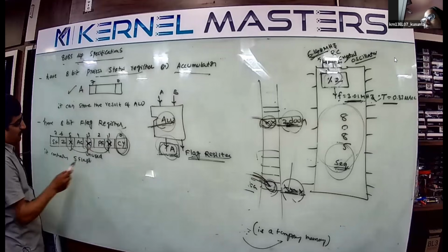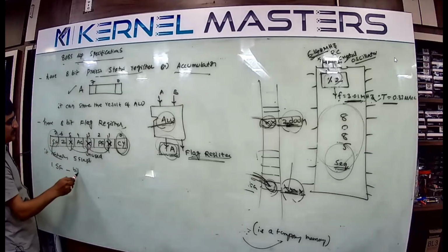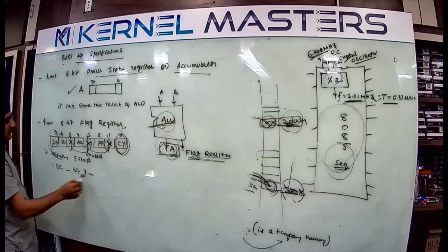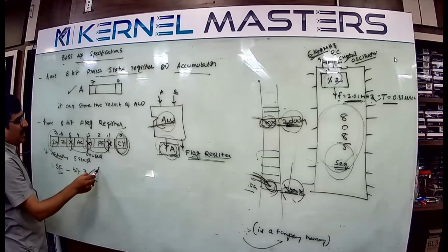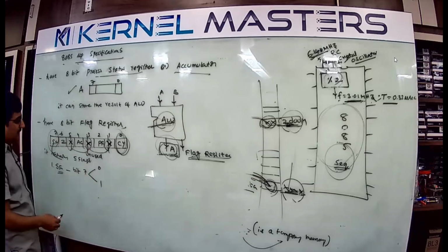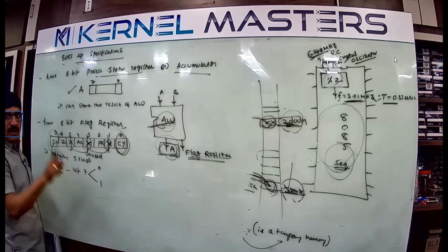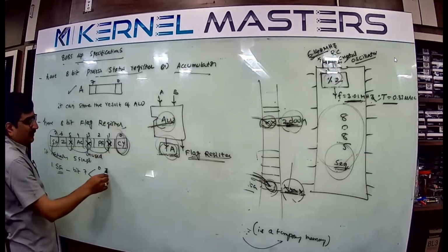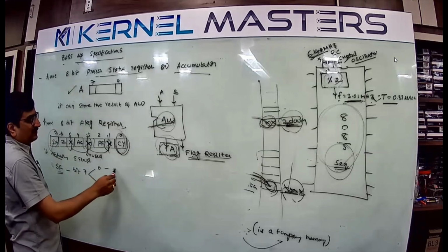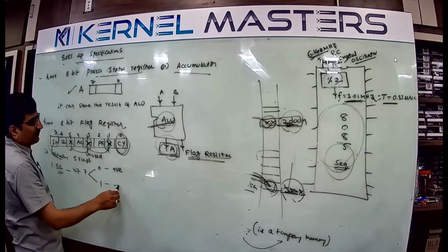The first flag is the sign flag, which is the MSB, at bit position 7. A flag has two states, on or off. If the sign flag is 0, the number is positive. If the MSB is 1, the sign is negative.